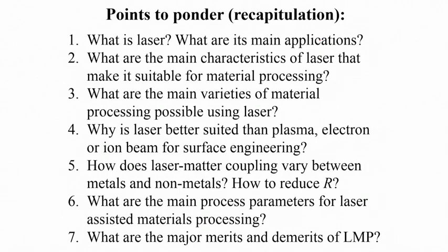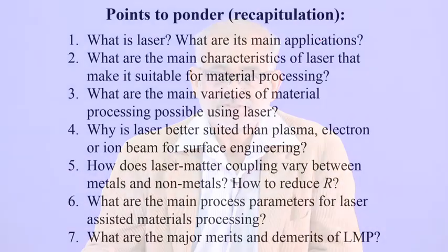So you require the beam to move fast, which is possible. Independently, one can change the speed or increase the speed, but you need a surface integration. You need surface integration, and you also need to allow sufficient interaction time for the heat to penetrate all the way to the other end. So if you want through and through, this is not an ideal tool for bulk heating. You'd rather use a furnace.